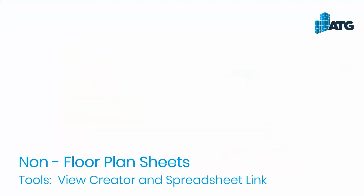Okay, so we have a ton of views and we have a ton of sheets. But so far we have only addressed floor plans and ceiling plans. What about the rest of the sheets? Let's say our company has a standard method of naming and numbering sheets, which most companies do, right? And let's say this data is updated in an Excel spreadsheet. So let's use this data that's saved out to quickly create the balance of the sheets that we will need for the project. Here again, we're going to use the View Creator and Spreadsheet Link again.